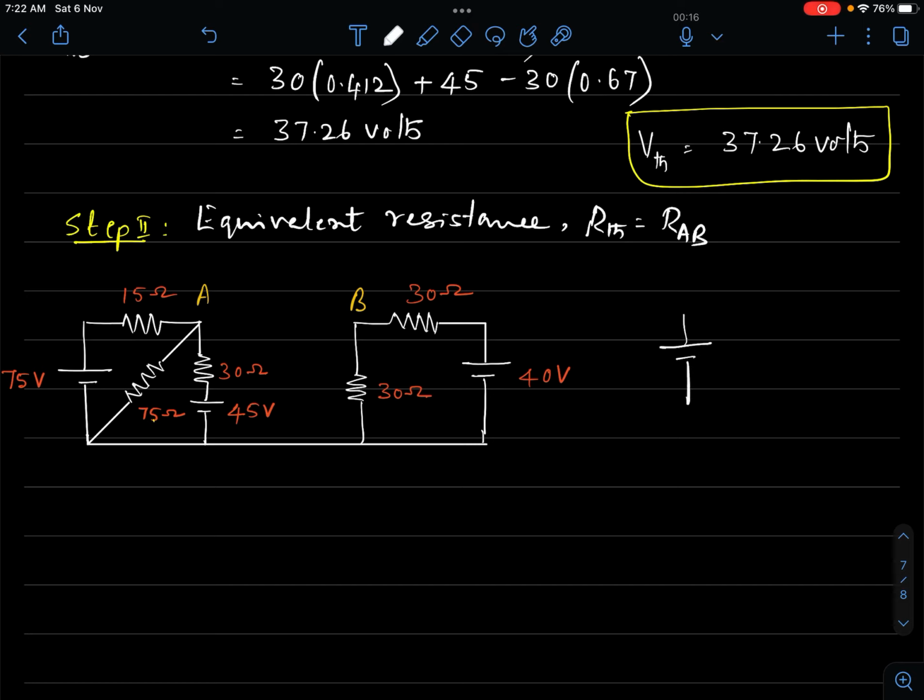So you have a voltage source, right? If you connect a voltmeter between the two terminals, whatever is the magnitude, let us talk about the 75 volt, it would record 75 volts. Even though I have not connected anything between the pair of terminals, no load is being connected, it is recording 75 volts. That means open circuiting a voltage source would still be considered on. The source is on. The source is not off. So we have to understand this very carefully.